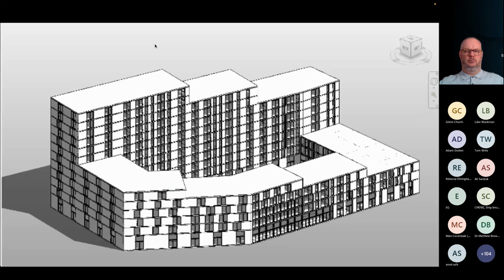And what you see here is already the BIM model with all the windows in place. And I will just pause over here, because if we were to jump to Spacemaker, you'd see this area over here with a huge window to wall ratio is where we would see the dark blue vertical sky component, right? You basically need to make it just glass. Where you see a lot of wall, that's where you have the light green. So that's really important, right?